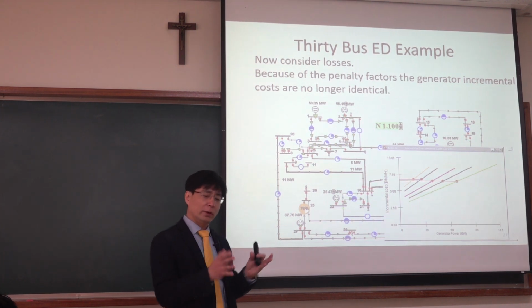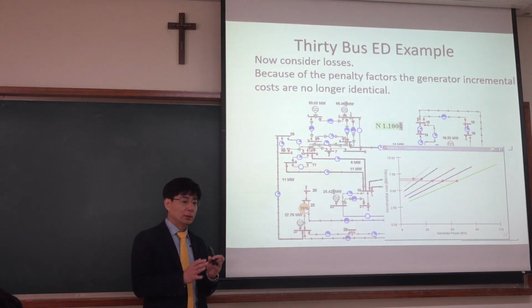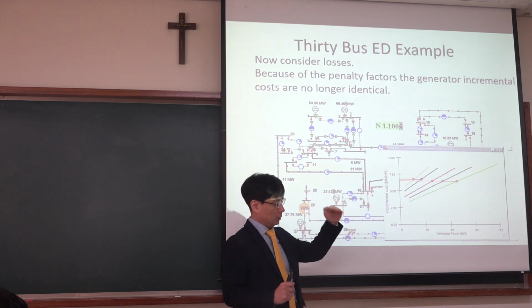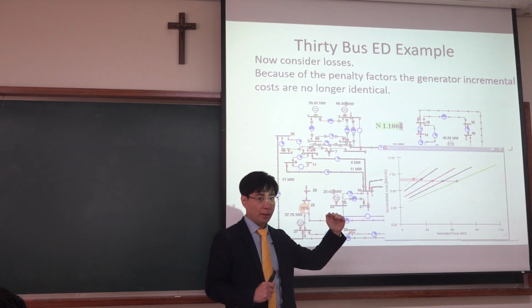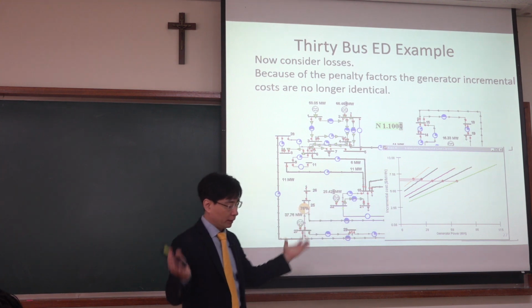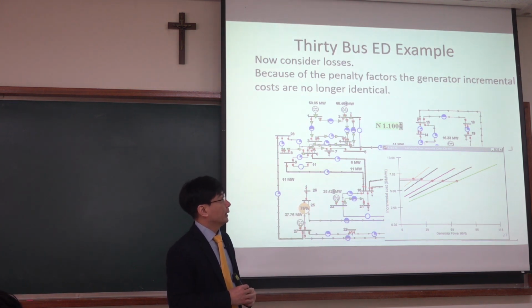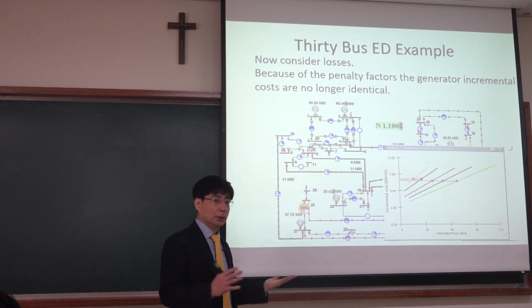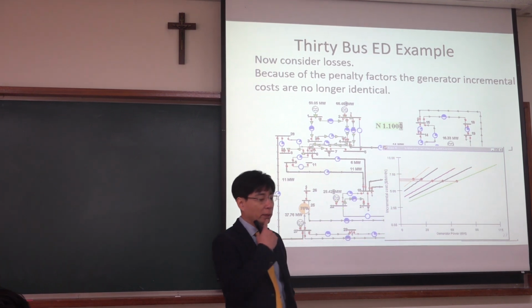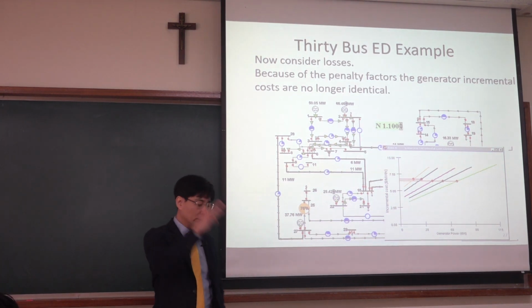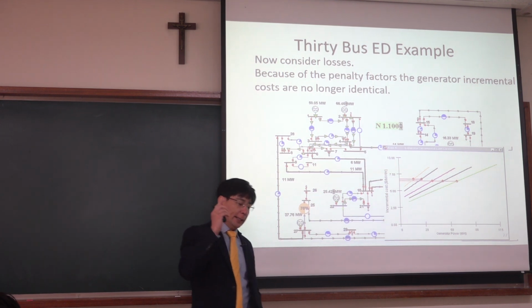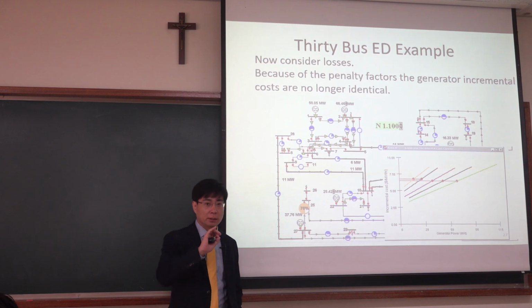And that is a very important part, because the problem happens when the transmission line meets its limit. And if more and more lines have that kind of limit condition, then that means we are very vulnerable to some kind of contingency. Also in that case, when many loads are heavily loaded, solving the power flow equation numerically may not be stable.